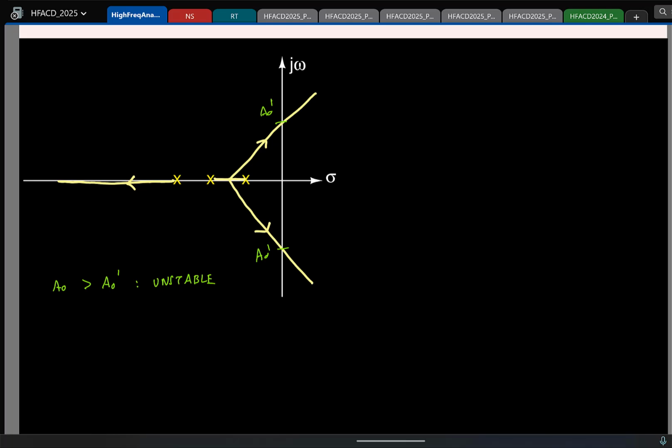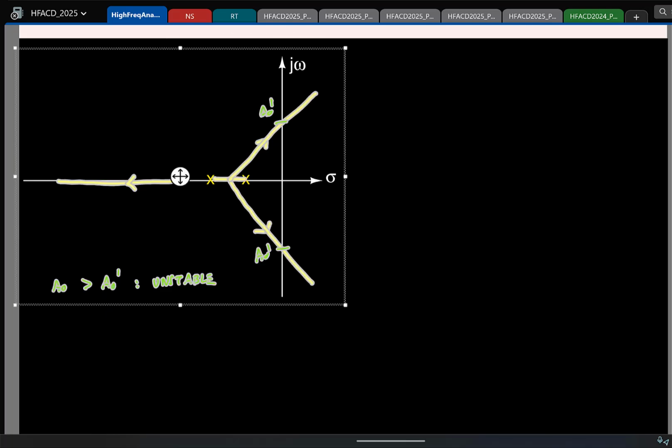And I will give it as an exercise to work out, and you will find that this gain, I mean, if the gain was, let's say, a million or something, it is okay, right? I can at least have a gain till a million and make sure things are stable. But as we'll see, this gain is pretty small. This is kind of useless if you have such a small DC gain. Okay, so now let me do one last case and then we'll wrap up root locus.